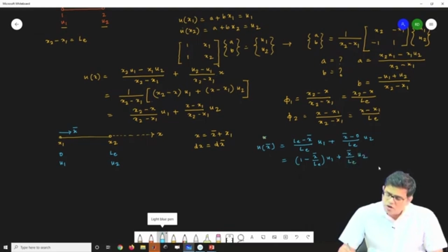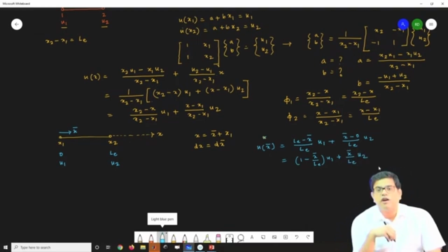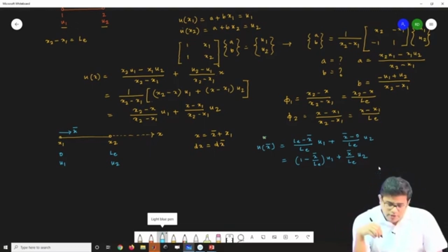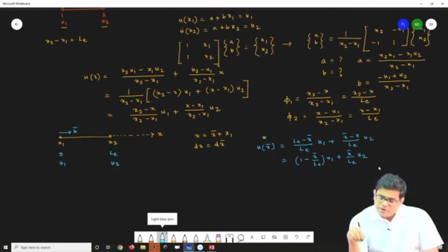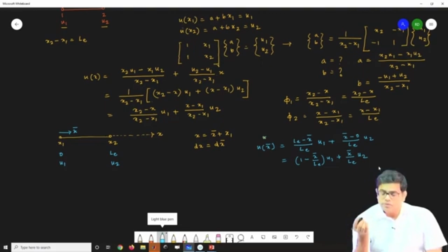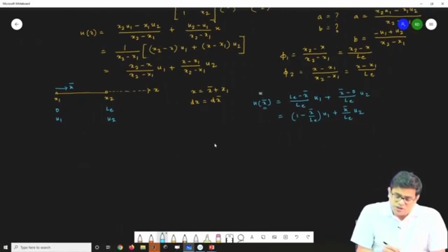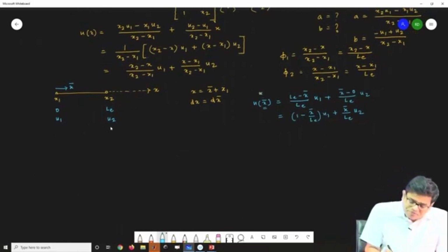So this is how my shape function varies within the element. So in case of dx or x bar quantities, I can really transfer them in terms of the local coordinate system. Notice here one thing, that this is dA x bar, so that's why we didn't substitute it here. Now if you remember our weak form, that is my Kij.